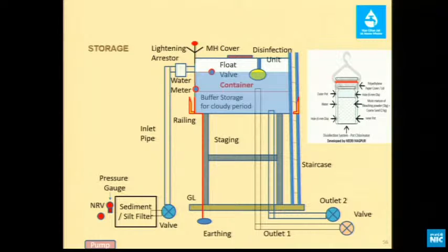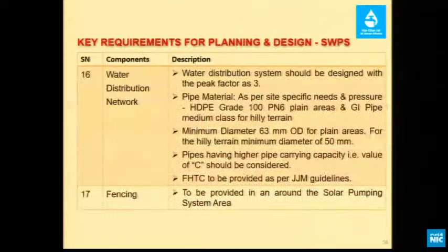And here I am showing one thing very clearly: a disinfection system developed by NEERI is very costly, but this one hardly costs you 200 rupees, and the filling can be done locally. This is moist sand filled in the container, and bleaching powder, and this yellow color is showing. We hang this system there, and in Chhattisgarh this is functioning very nicely. So it hardly has a cost. This disinfection system is there.